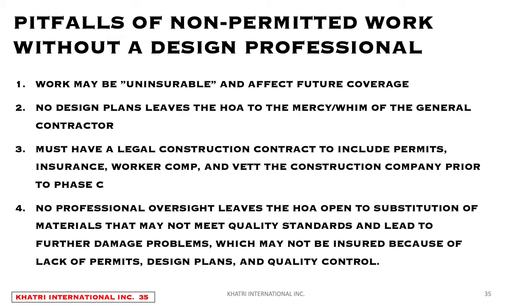And I know I've said it before, but I'm just giving you a short list here of the pitfalls because I see this so many times where people try to cut corners and they try to get the work done without a permit, without a design professional. And again, these are the risks. Your work may be uninsurable. It will affect your future coverage. No design plans leaves you at the mercy or the whim of the general contractor because you don't have a design document to go back to. You don't have a set